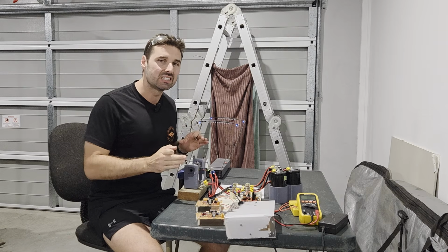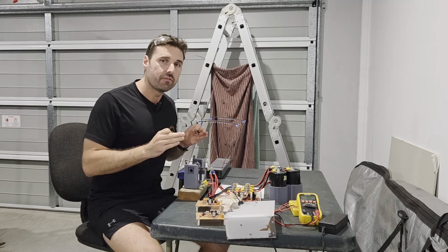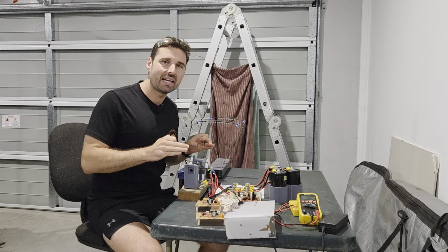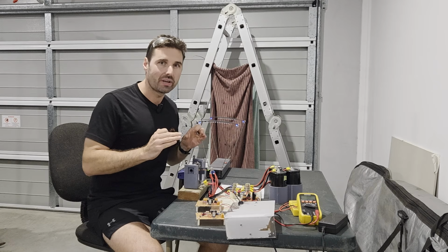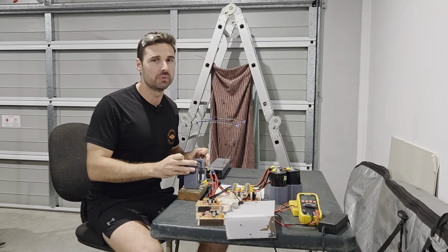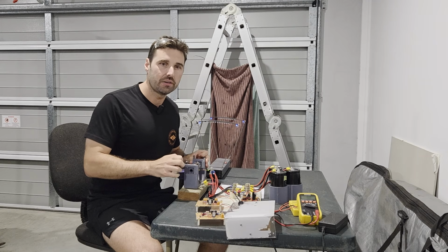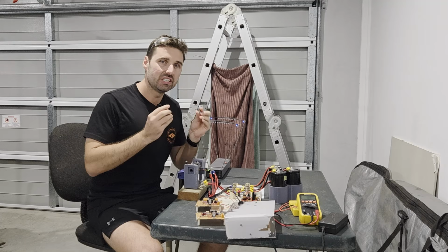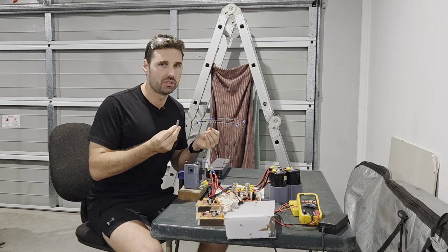Now we have seen how the inductance and L to R ratio affect a coil's current flow and therefore its output. We can now look at a case where having a higher inductance while keeping the same coil dimensions and resistance may provide a performance gain. This is done through the material choice for the projectile, in particular using a material with a higher permeability.